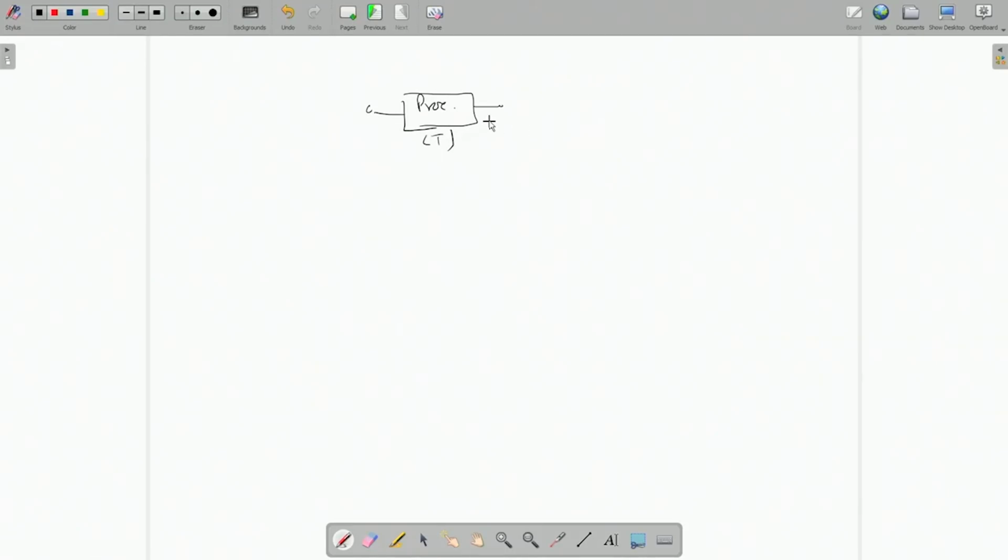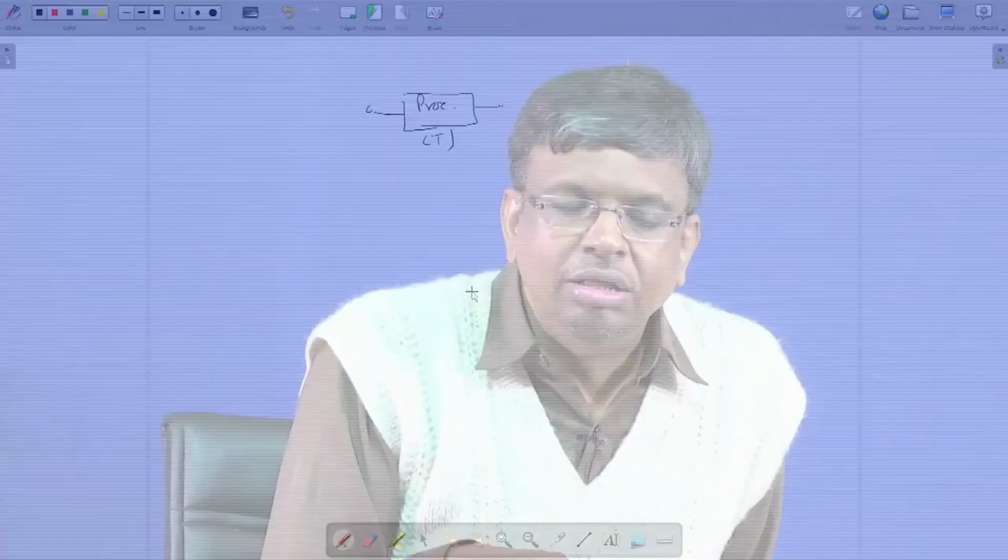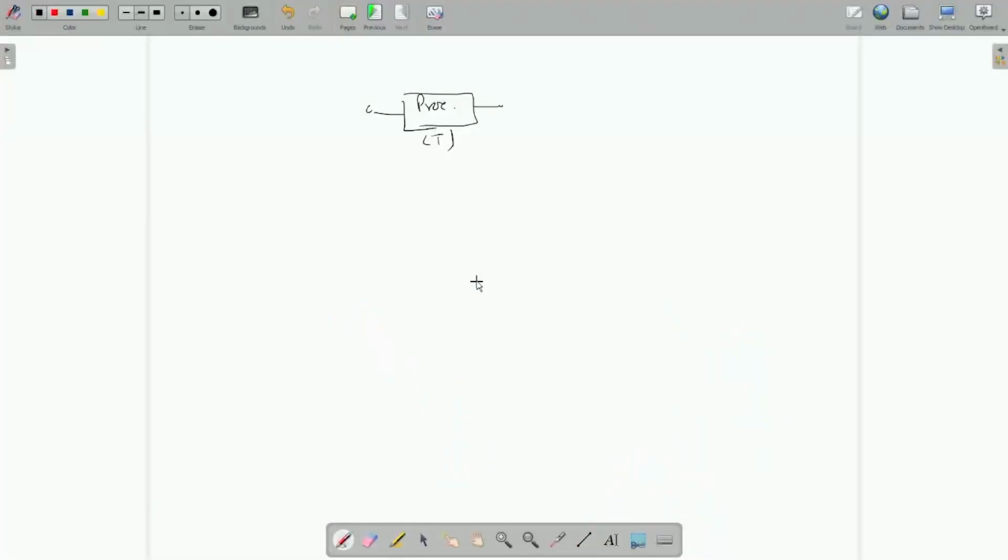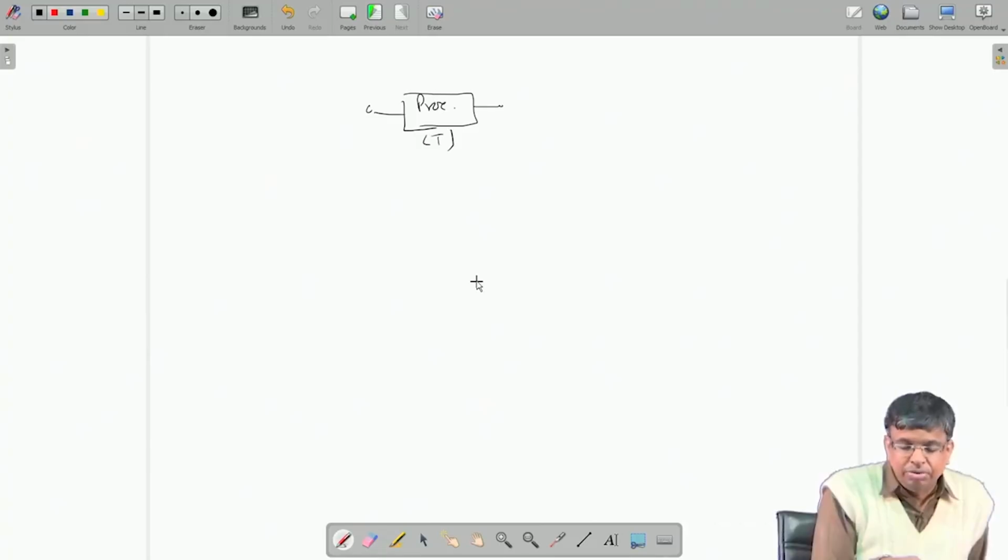If you want to bring up the input output rate by a factor of j, that is reduce the period by a factor of j, the system clock won't go up by that rate. So, I need to make j copies in parallel. That has one disadvantage, that whatever hardware it takes gets multiplied by j, and whatever power it consumes gets multiplied by j, right.